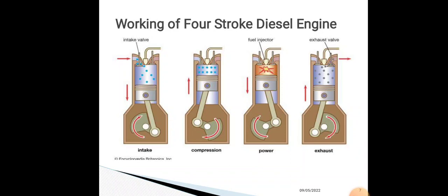Then the last figure indicates the exhaust stroke. The piston traveling from BDC to TDC pushes out the products of combustion. The exhaust valve is open and the intake valve is closed during this stroke.